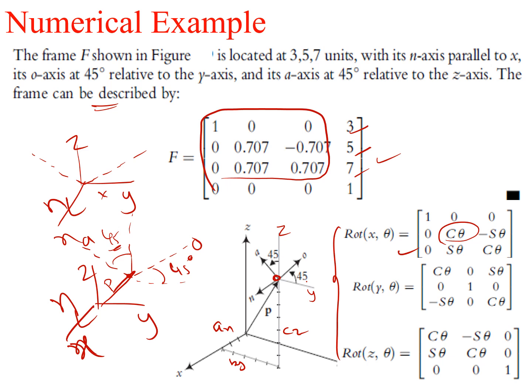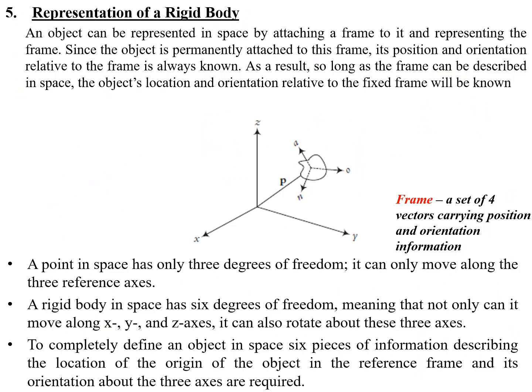So like this we can represent a frame. This robot frame is nothing but one of the robot frames. Likewise you can say where your robot is, what the orientation of the robot is, and what the position of the robot is, using this homogeneous matrix. Once again I'll repeat, a homogeneous matrix is a 4 cross 4 matrix. In this you have the rotation matrix, whose order is 3 cross 3, then the translation matrix, whose order is 3 cross 1, then 0, 0, 0, and one scaling factor. So likewise we can represent any frame with respect to the world frame.